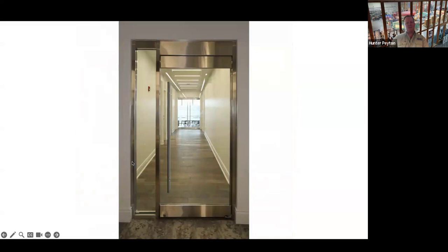Okay, so this is an example of a 42-inch door. One thing I haven't touched on is the doors come in 42 and 36-inch widths. This is a single, obviously, and we put this in as a 42 because it maintains the ADA compliance. The 36s are either right at or right under what would be considered compliant for ADA. So anytime a client wants to put in a single door, we strongly recommend that they use a 42-inch door.